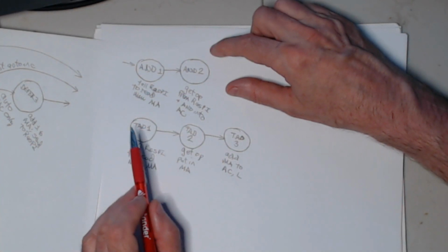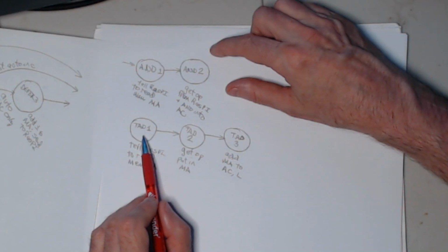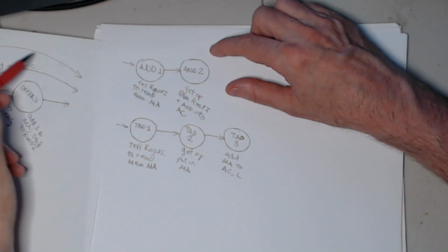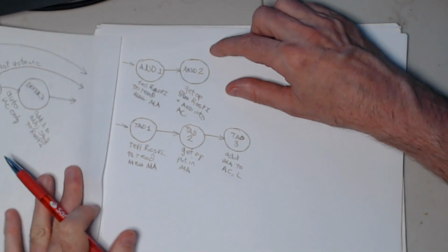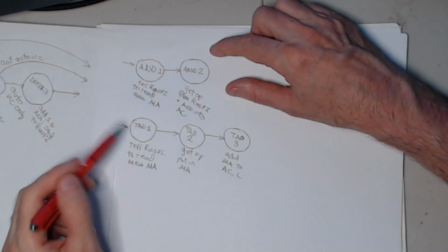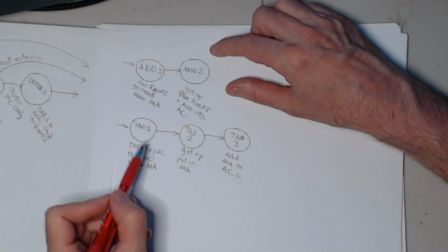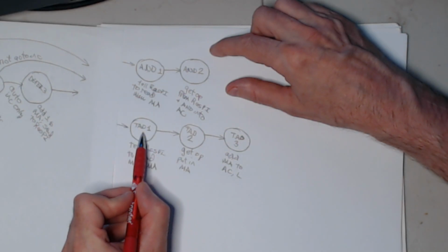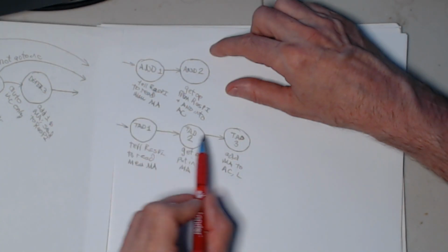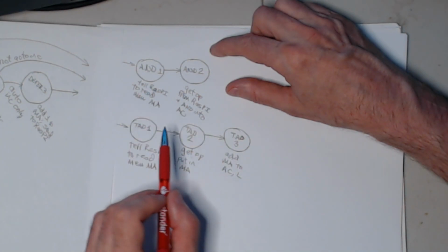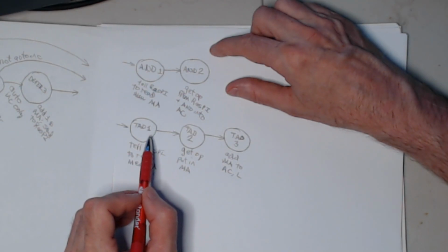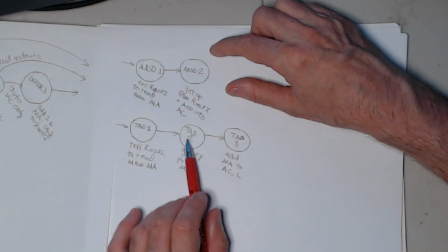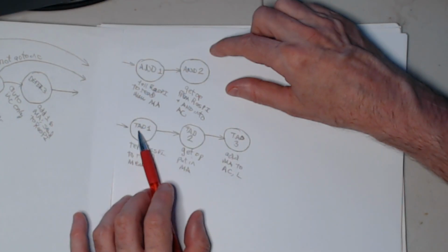Now, one thing about TAD, again, it can come from any one of these 3 here, right, if it's a TAD instruction. One thing about the TAD instruction is it is used a lot when the accumulator is 0 as a load, just to load a value into the accumulator, and it takes 3 cycles, that's kind of silly to take 3 cycles.